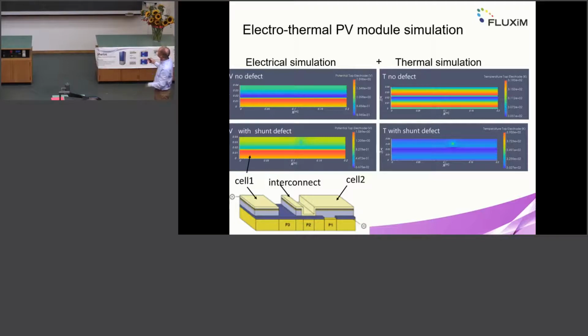this sketch is a bit cut off. In reality, the solar cell is extended maybe 1 centimeter wide. So the current is being collected vertically and pulled to the left. And on this left edge, we have all the current density concentrated. So along this line we have this higher temperature. That's the reason for the elevated temperature along this line: the current is collected on this edge here. The current comes from the left and goes here.